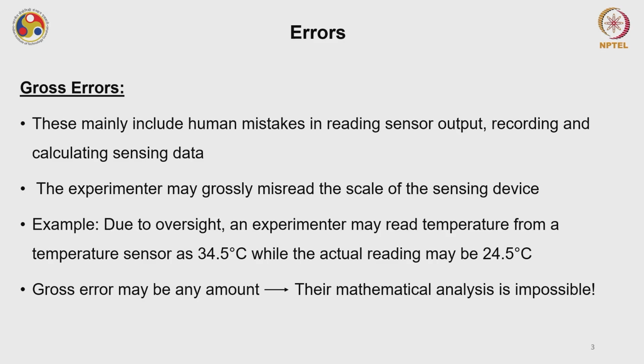The electrical output is in the form of current, voltage or charge. But we have to interpret from that current or voltage to some physical parameter. Say, for example, consider a temperature sensor. The output is in the form of some microvolt, right? Now, I have to interpret this microvolt for a certain temperature. So, it also includes that kind of error, interpreting error.